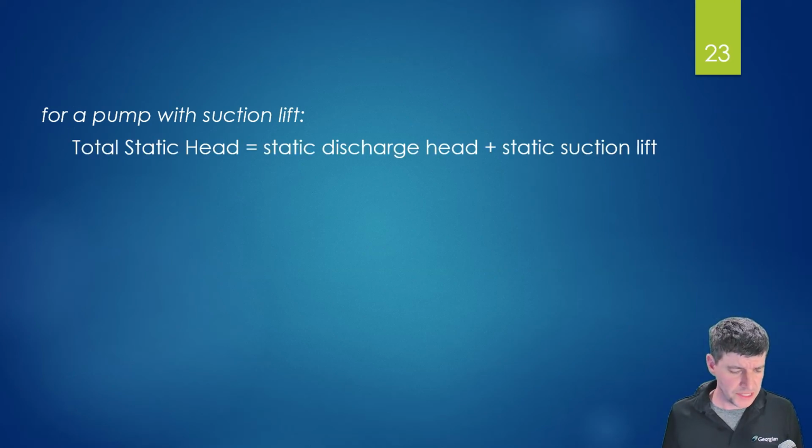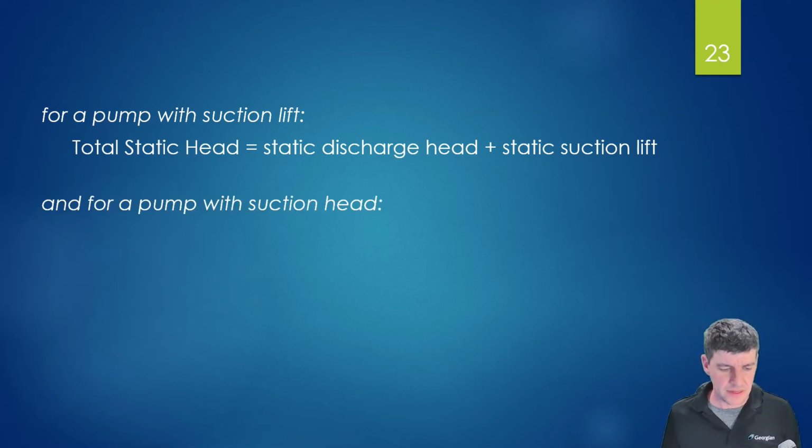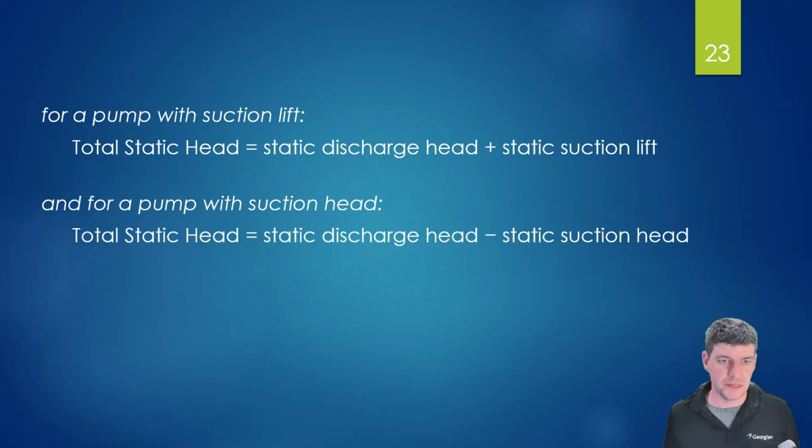So as I was saying, your textbook outlines, make sure you memorize this. If you have a pump with suction lift, then total static head is going to be the static discharge plus the static suction lift. But if you have a pump with a suction head, then of course it's going to be one minus the other. And if you can draw the diagram and relate that, then that's one way you can remember this stuff.